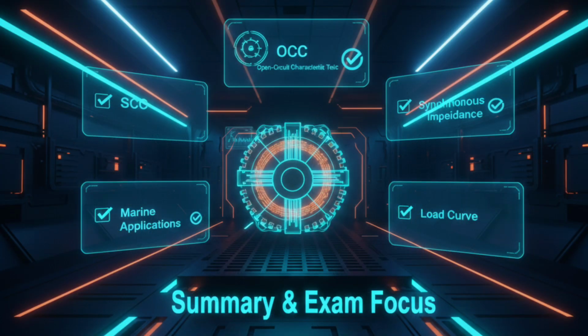Summary or exam focus. Let us conclude this lecture. Open circuit tests give us the OCC curve and show how voltage builds with excitation. Short circuit tests produce the SCC curve and allow calculation of synchronous impedance. Combining both helps predict voltage regulation and load performance. These methods are fundamental in marine and industrial alternator testing.